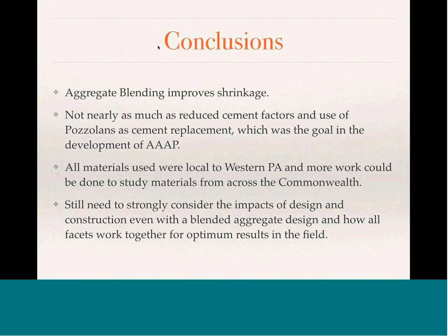Some conclusions from this. Working on a full report with commentary on everything that we worked towards. Once I get that wrapped up, I'll get that to Rich. He'll be able to distribute it to the group. Just some conclusions. Aggregate blending does improve shrinkage. We saw that. Not nearly as much as the reduced cement factors, which was ultimately the goal of AAAP.